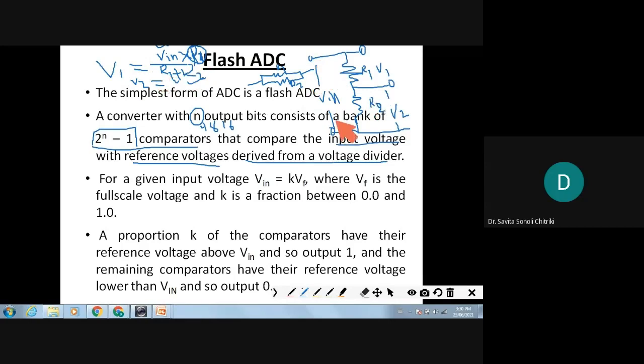So now you know the main V in. Think now I have the analog voltage as 5 volts. Then next I have used the voltage divider there. N number of resistors are being used. Whatever the drop will be there is connected to the comparator. So the input voltage and the reference are compared, and depending on that the output is generated, which is greater or lesser. So that's what I was telling.